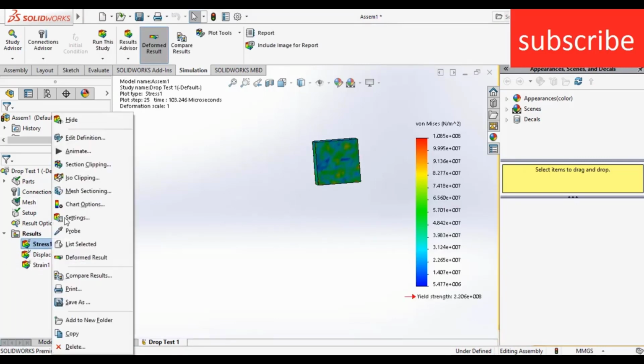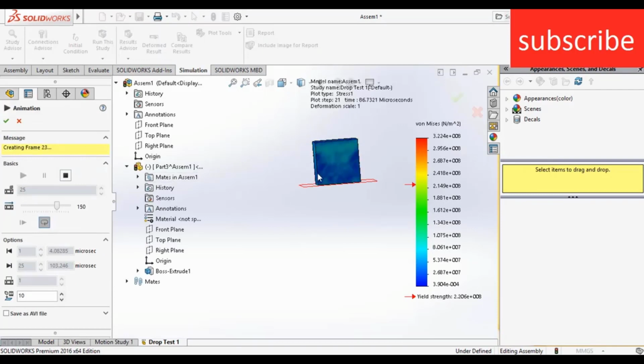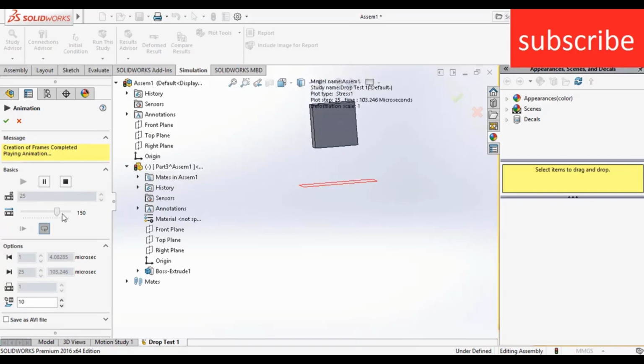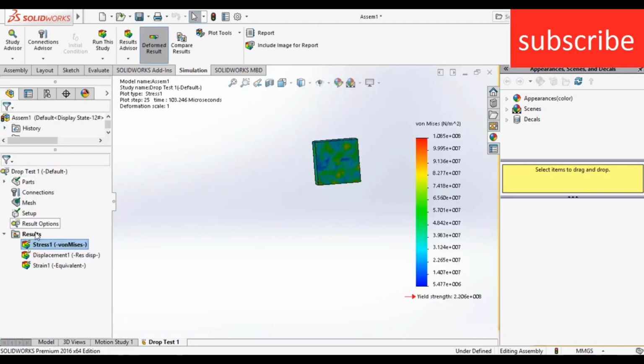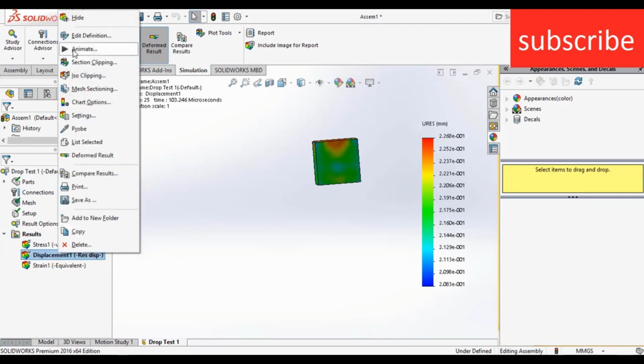Now right click on stress, click on animate. Here you can see the animation. Click OK and right click on displacement, click on show and right click on animate.